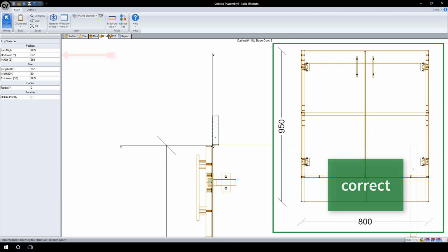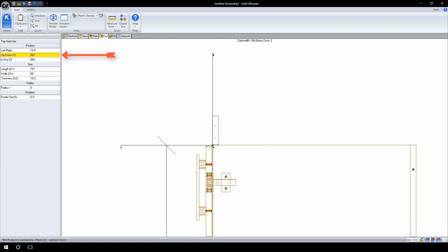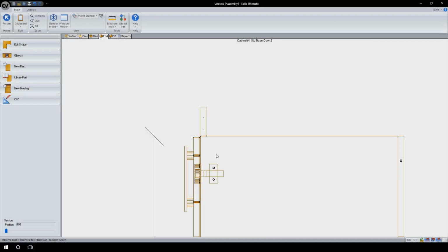This is where we need to change this Y value to an equation, so it will always correctly place its own width underneath the top cabinet height. I need to identify what values I need to grab: the cabinet height, or dy, and the top stretcher width, or the dx of the stretcher. This is because if the construction method ever redefines the width of my stretchers, I need to ensure that it will correctly reference its own width for the purpose of how it places itself in the Y-plane.